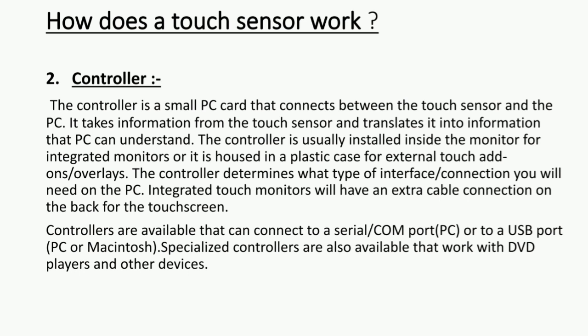The controller is usually installed inside the monitor for integrated monitors, or it is housed in a plastic case for external touch add-ons or overlays. The controller determines what type of interface or connection you will need on the PC. Integrated touch monitors will have an extra cable connection on the back for the touchscreen. Controllers are available that can connect to a serial or COM port or to a USB port. Specialized controllers are also available that work with DVD players and other devices.